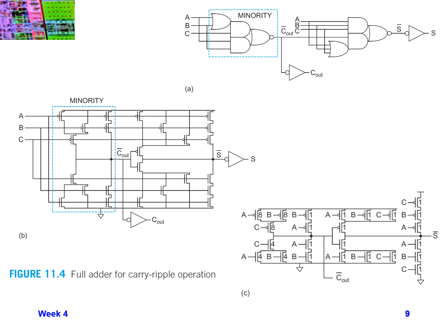The sum needs to wait for C out bar to come out from this stage in order to generate the sum in a single stage plus the inversion. But again, the sum isn't typically the critical path in our adder, and so we get the C out bar pretty quickly in the single stage, which is what we care about.